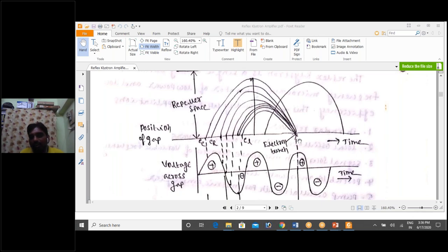After forming all of these into one electron bunch, we complete that one cycle. Again we go to the next RF signal, again positive, 0, negative, and we can form another bunch. This is done continuously, with electrons moving from the input side to the output side in the form of bunches, both input and output measured at the same place.